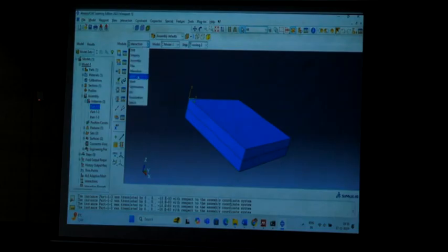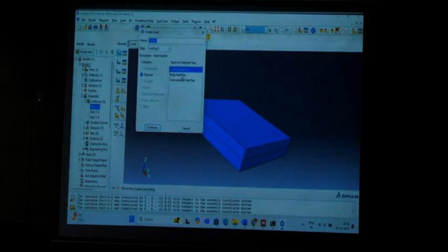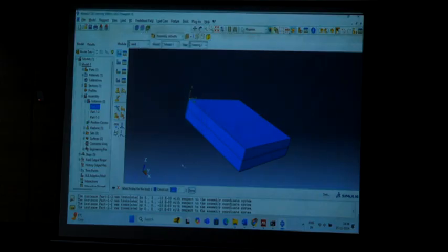Now we will go to load. Whatever the load we are going to give, first the boundary conditions. In this case, since we are working on heat transfer, we will just give it as a heat flux. Go to thermal, here we just need to go for the heating one. Go to continue. It will ask you on which surface. We will say this one. Sorry, all things.